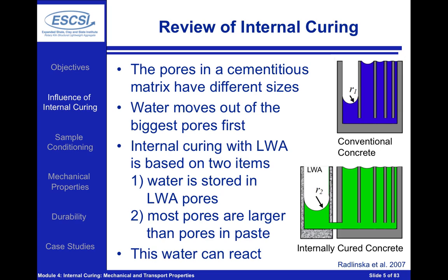Internal curing using lightweight aggregate is based on the principle that water is going to be stored in the pores of the lightweight aggregate, and those pores are larger than the pores in the paste. So if we look at the diagram toward the bottom here, the whole concept is that water will leave the lightweight aggregate and fill in the pores in the paste.